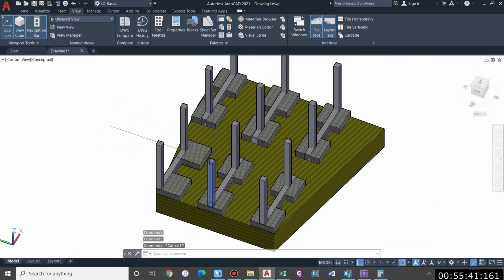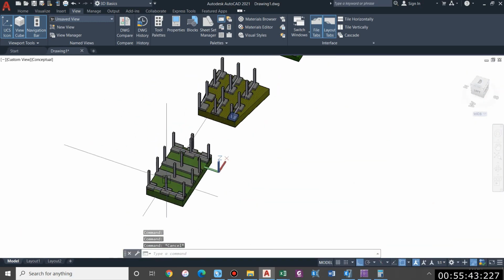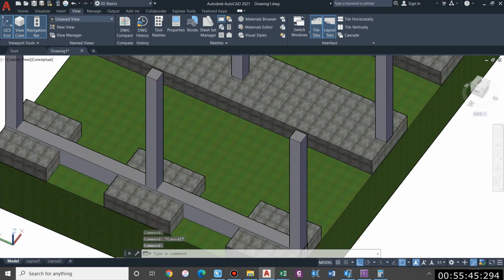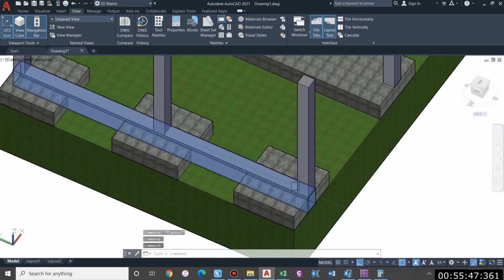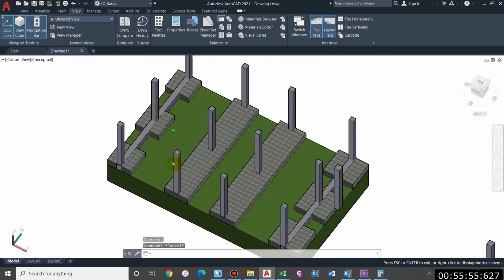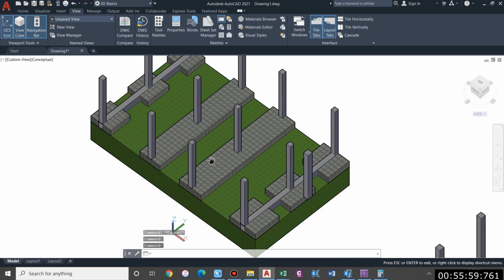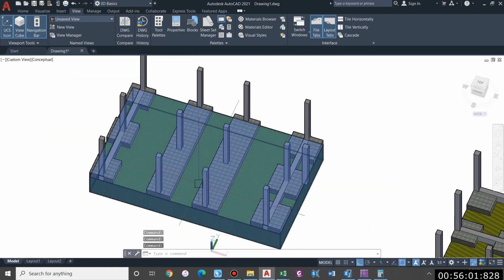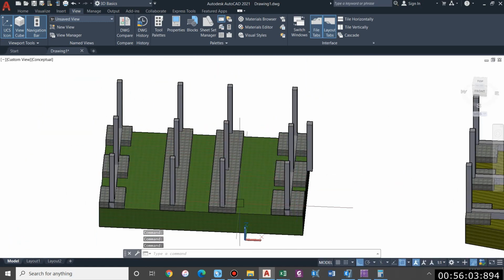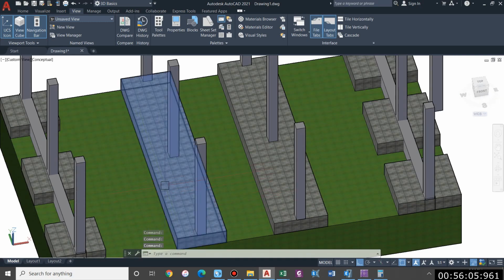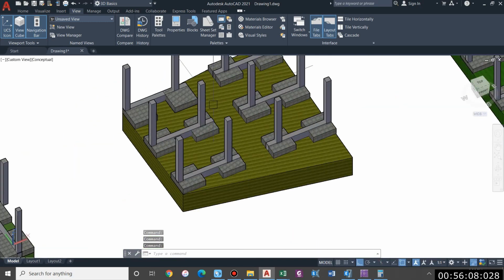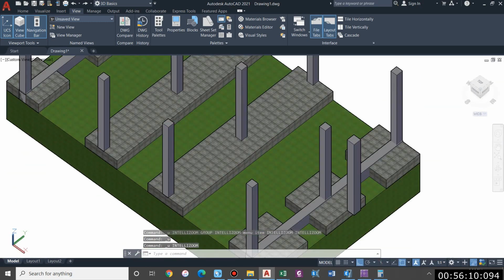But what can be done is, if there is a central footing in the middle and eccentric footings on either side, then these two footings can be connected through a strap beam with the central one, which is what I have done in this case. And again, if the loading increases for the interior column, the loading will be more than that of the outer one, so I have provided a combined footing for this. So now we'll understand how to design a mat footing.